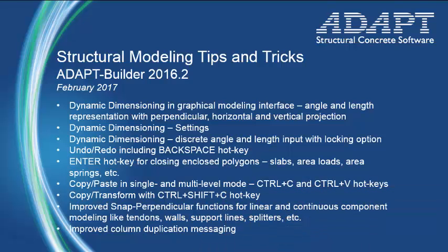The Enter key can now be used for closing closed polygons like slabs, area loads, and area springs, instead of having to select the C button to close or right-click and select Close. The copy and paste functions in the program, using hotkeys Control-C and Control-V or from the Edit menu, have been improved in both single and multiple level modes.